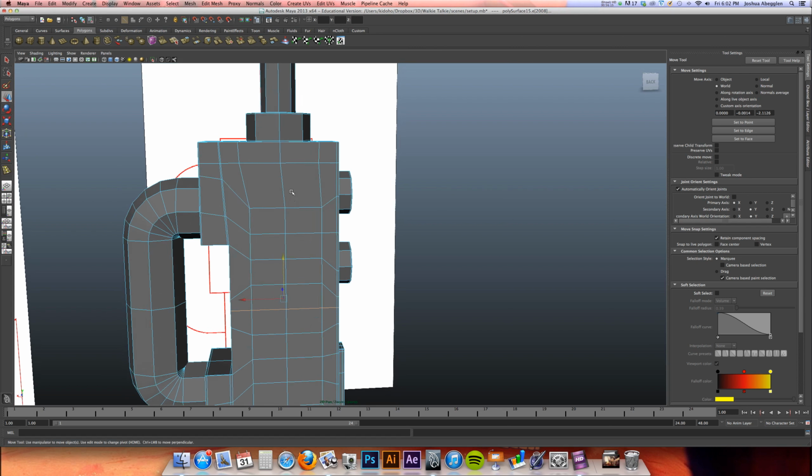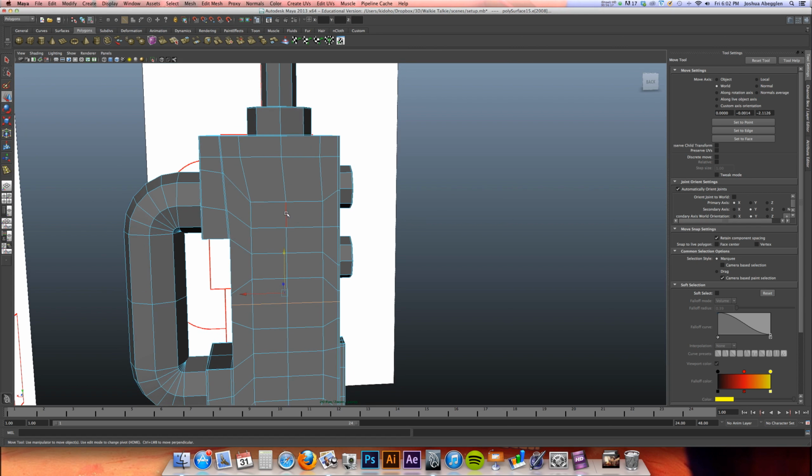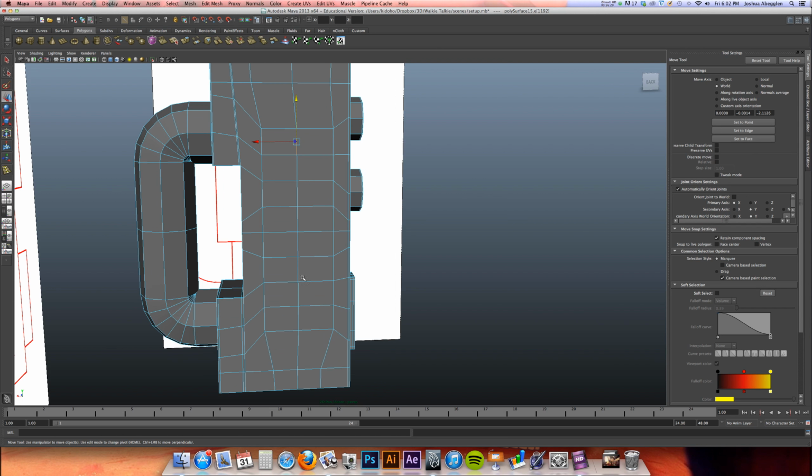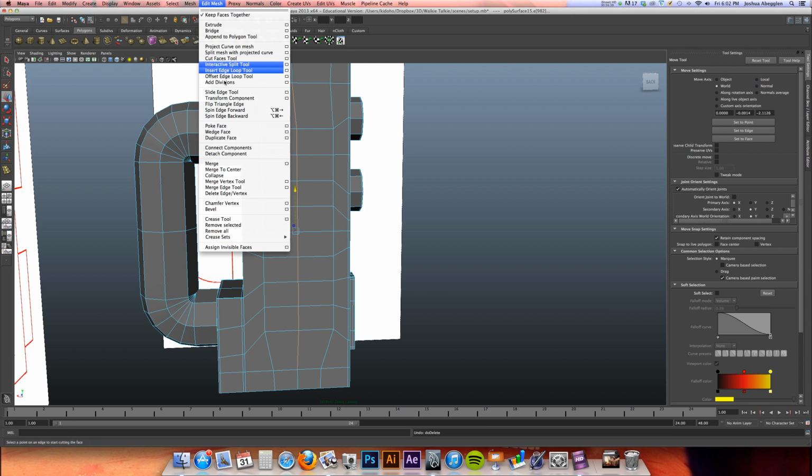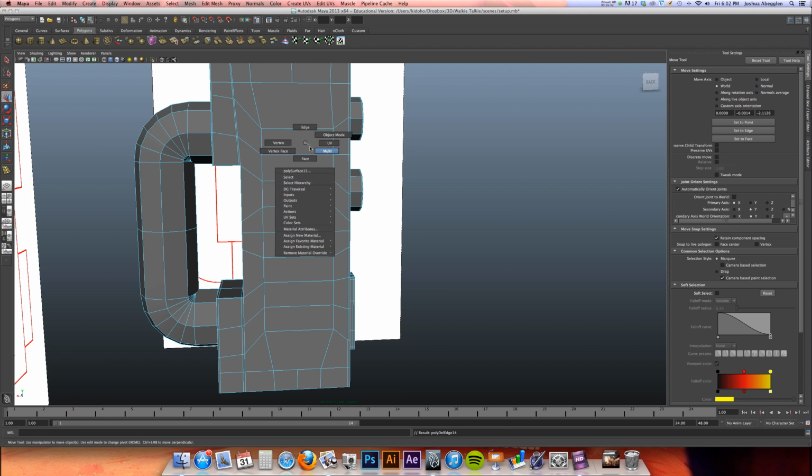Okay, for the moment, I'm actually going to grab this edge here, hold down Shift and double click and bring it all the way down to here and grab that edge. Actually, you know what? I'm going to do it beyond that point. And I'm going to delete those. Actually, not delete those. Let's go ahead and do the delete edge and vertice, because what I want to do is grab each of these 8 faces unencumbered by that additional geometry.